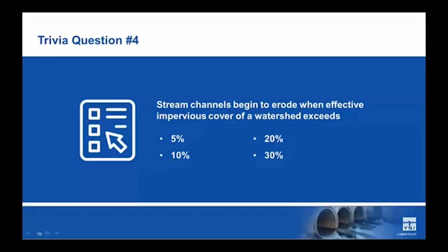And very often with our fully integrated systems, there is some programming that needs to happen in a data logger to get compatible data movement into a SCADA program. That is so important in stormwater monitoring. And what we have found, what experience has taught us, is that all SCADA programs seem to be different. It seems like the way one city is implementing and using their SCADA is quite different than the city down the road.